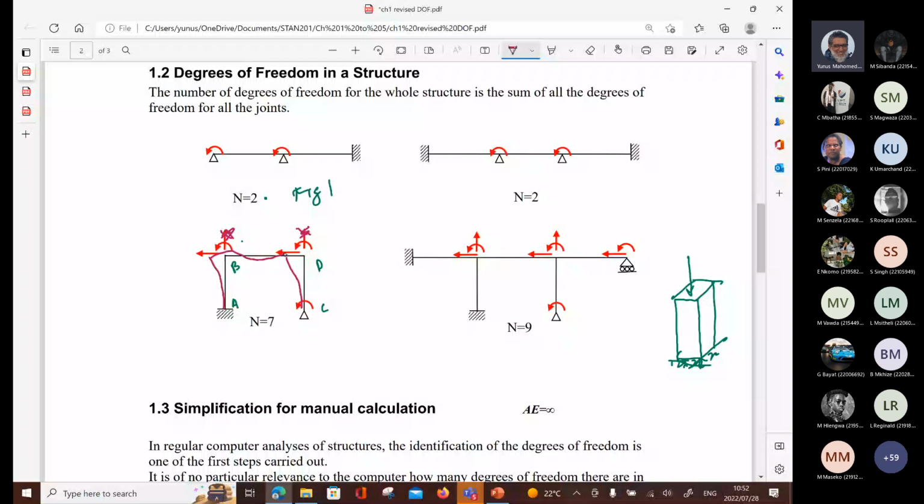Are they different? Remembering that BD is something very, very stiff. It's got infinite stiffness. Stiffness is measured with inertia divided by length, right? So it's infinitely stiff. I've got a big fat section, and it doesn't really get flexible, or it doesn't shorten or elongate in a hurry, right? So when I move these two, what you can do is take your ruler, put it between your hands, right and left hands.